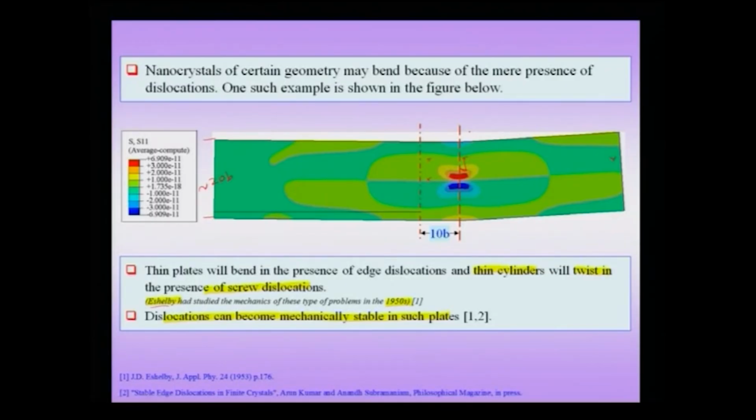So, I have a dislocation in a normal crystal. Suppose I draw a normal crystal like this, a dislocation here will feel a force towards the free surface, but here if I put a dislocation somewhere here, then it will actually feel a force toward the center, the mid plane of the domain, rather than away towards the free surface. And of course, you have to demarcate a region where this is stable.